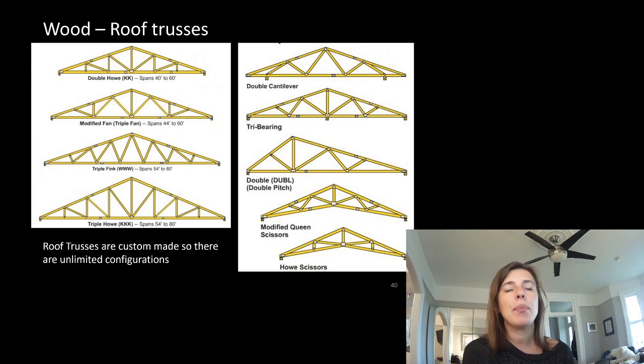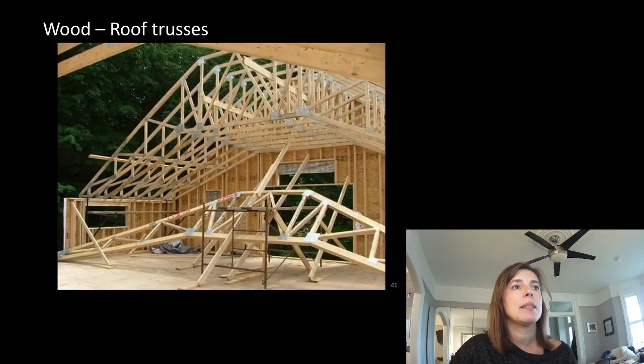Roof trusses. I don't get hung up on truss names. I think the engineering will just shake out. The reason why I don't get hung up on names: how many configurations of trusses are there? Unlimited. You outline the profile, and we can come up with the infill that is the most economical and most engineering efficient. So here are a few names with a few different types, but you can start to get into all kinds of kooky things. So they are custom made, designed to specific criteria, and there are an unlimited amount of configurations.